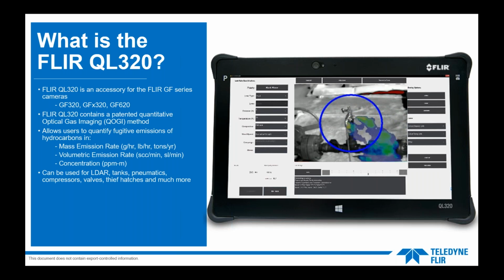And it contains a patented quantitative optical gas imaging method. It will allow you to quantify fugitive emissions of hydrocarbons in either a mass emission rate, volumetric emission rate, or concentration, and can be used for leak detection and repair, looking at tanks, pneumatics, compressors, valves, thief hatches, and many, many more.